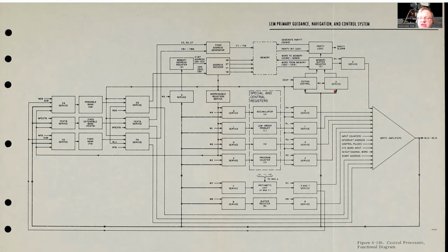We talked about that G register, the memory buffer register, and this is what handles data going from memory and out. When we say out, we have our write bus or our data bus within the AGC. This is where we think of things like write amplifiers, because again, we're not going to be implementing it using some of the more primitive technology that was used during the construction of the Apollo guidance computer. We don't really have to worry about write amplifiers and sense amplifiers and things like that when it comes to running data onto the bus.